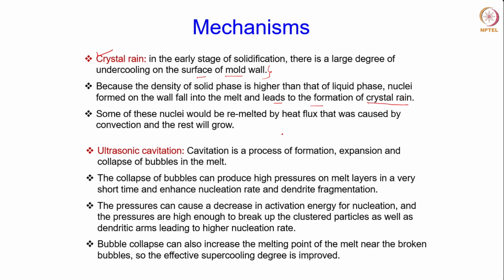Okay, so if you have looked at the microstructure in a mold, as to how the grains solidify, you would see that near the mold you have a high undercooling because the mold leads to a chilling effect, right? Here the heat transfer rate is much higher, the cooling rate is higher, okay? So therefore it will immediately nucleate the solid grains as fine nucleus grains along the mold walls.